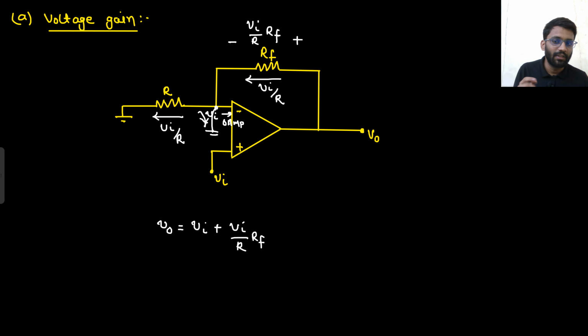Are you getting this point? So similarly, V in will not take up any current. It is just the potential of that particular node. The potential of that particular node is V in. That's why it is called a virtual short. Both the inverting terminal and the non-inverting terminal are virtually shorted, not exactly shorted. They are not actually shorted, they are virtually shorted. Say yes or no. Understood?